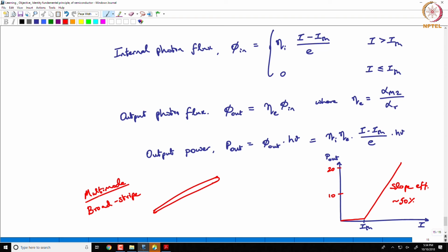So, the lasers that we use are all multimode lasers. They are actually coupled into a multimode fiber. Each laser is giving about 10 watts of power, and I have multiple lasers stacked on top of each other, and overall the emission starts looking like one large beam. So, you can use some optics to shape the beam and then couple it into a multimode optical fiber.